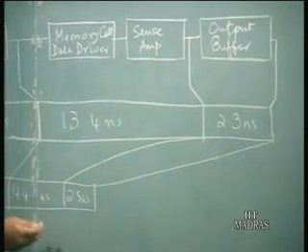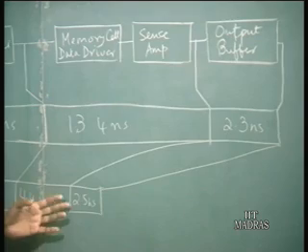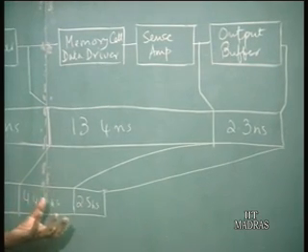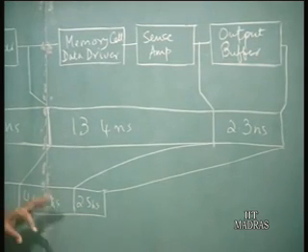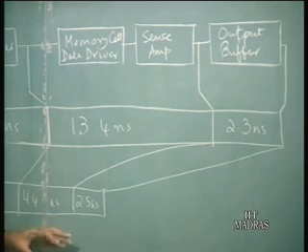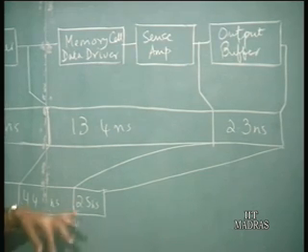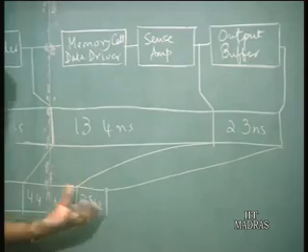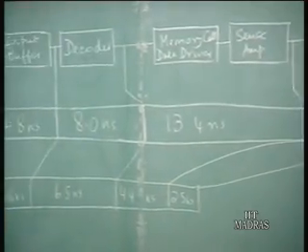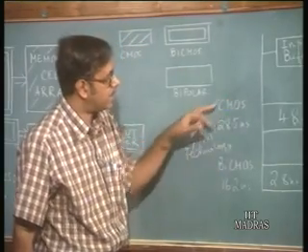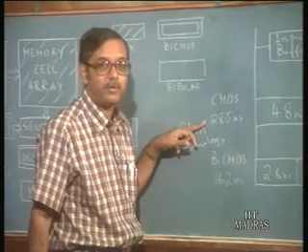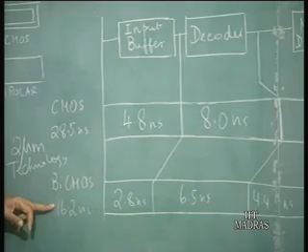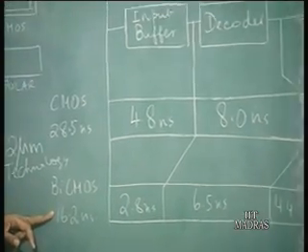increased to 2.5 nanoseconds, because again, in the case of a BiCMOS, you have to convert the CMOS levels to ECL levels. So, there is a slightly larger delay, but if we compare the total delays for the CMOS, while it is 28.5 nanoseconds, it has gone down to 16.2 nanoseconds for a BiCMOS.